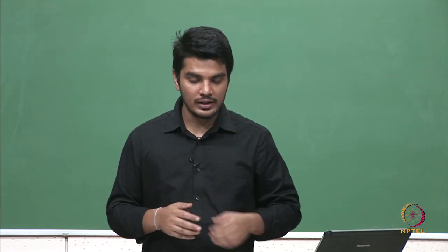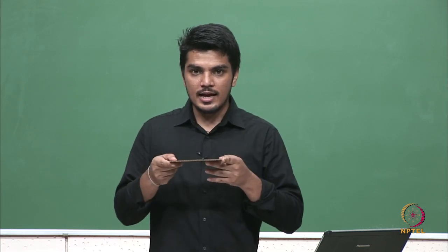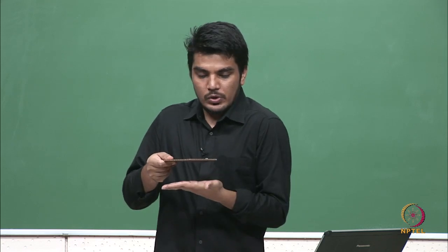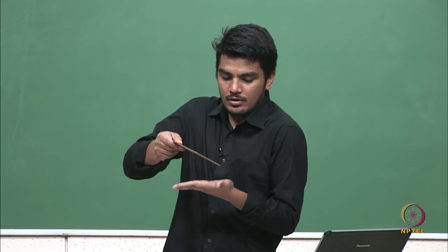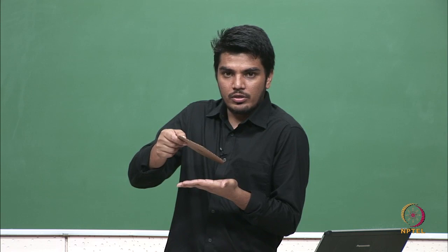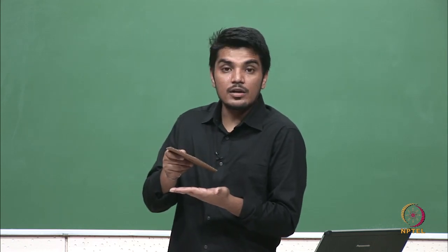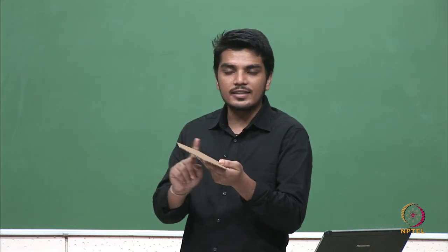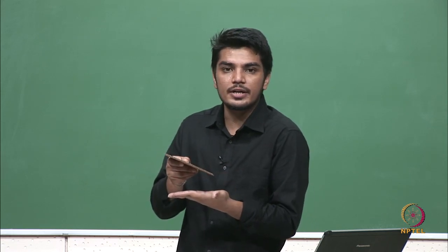Now moving to the second orientation. In this we have this regular hexagon. This hexagon is rotated about this axis to a 30° angle. The first orientation is this. Now rotating about this axis to a 30° angle, we get this. This is the second orientation, and for this orientation, on seeing from top, the shape of the hexagon we obtain is not the same as that in the first orientation, but on seeing from front we will get the same straight line of the same length, but now it is oriented at a 30° angle.